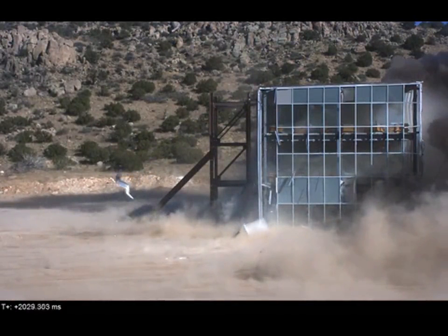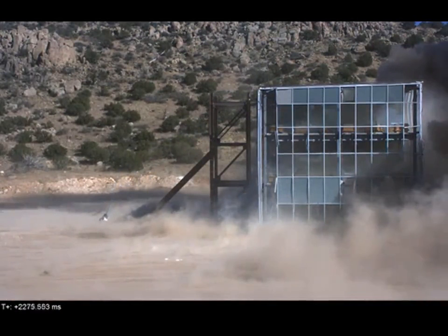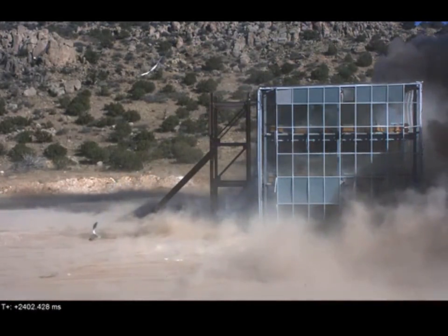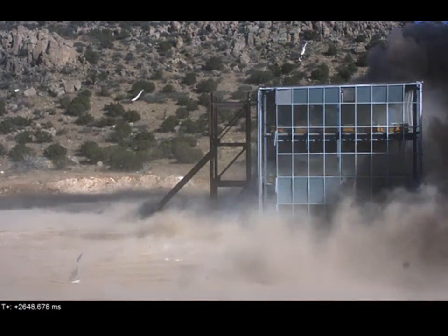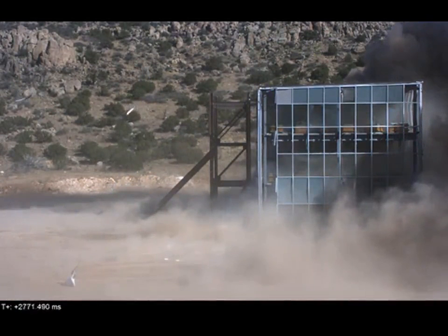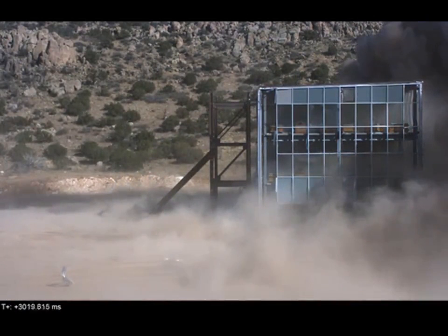The final two points that I want to make are, first, that in an actual blast-resistant building, the envelope is the first line of protection. So a lot of the structural elements that make up the lateral system and the gravity system are protected from the blast loads. So when you're designing a building, you're going to be concentrating on the exposed elements, which generally occur in the roof of the building.